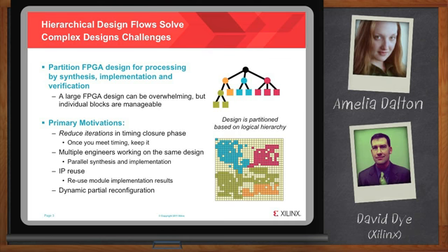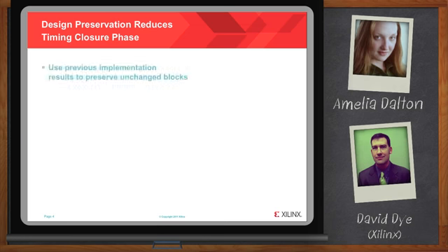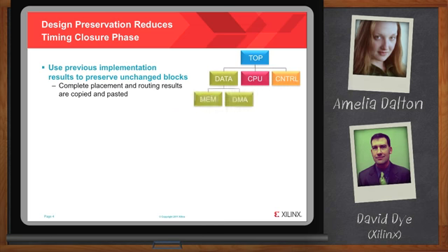Oh, okay, it's easy. As the name implies, hierarchical design requires partitioning the design based on its logical hierarchy. You'll see the best results when related logic and critical paths are grouped within a single bundle. So an example here, if I have a DMA controller that needs to have a tight connection to a memory module, put these 2 blocks together under a common level of hierarchy and place a partition on that level, as shown in green right here.